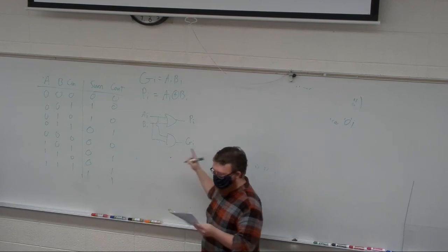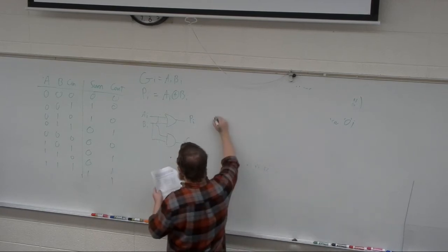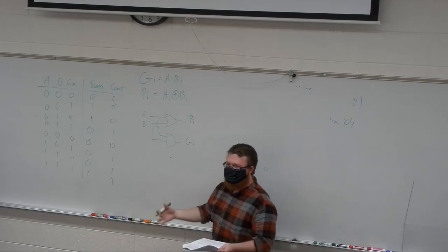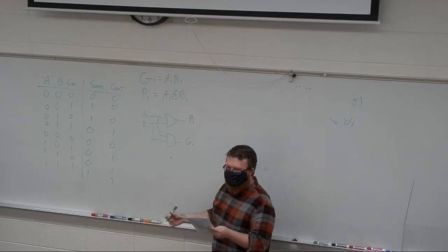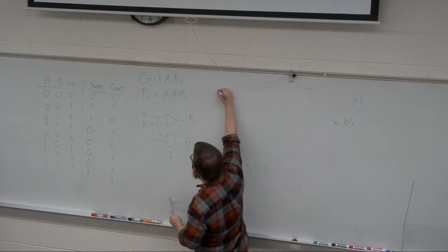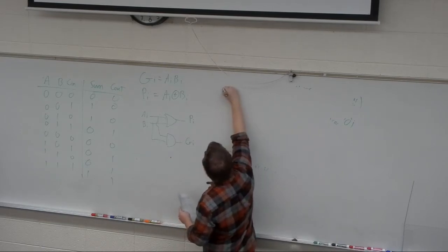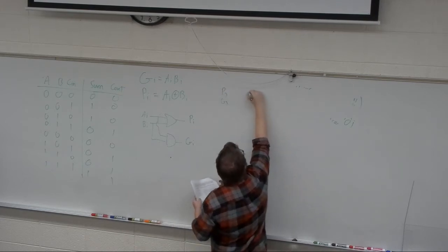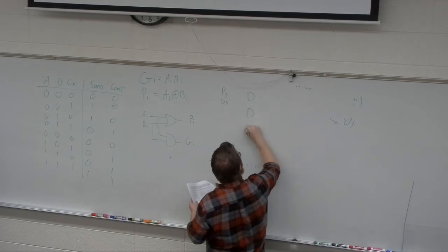Phase one. Step two, you can go on to then create all of that next tiered logic, right, which is the ANDs and ORs. So in the case of P3, say, for propagate 3 and generate 3, you need 3 AND gates.